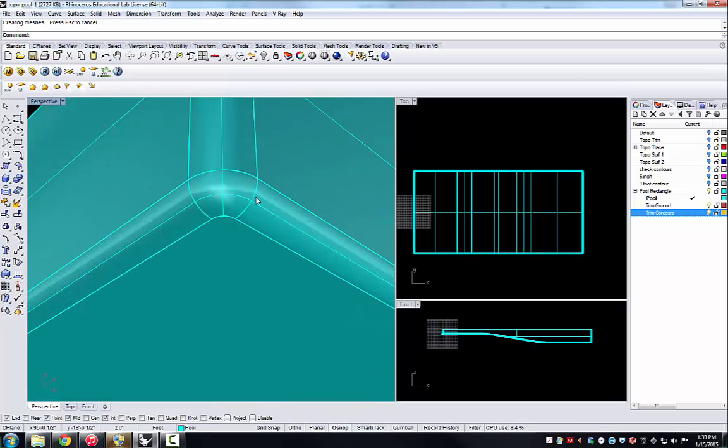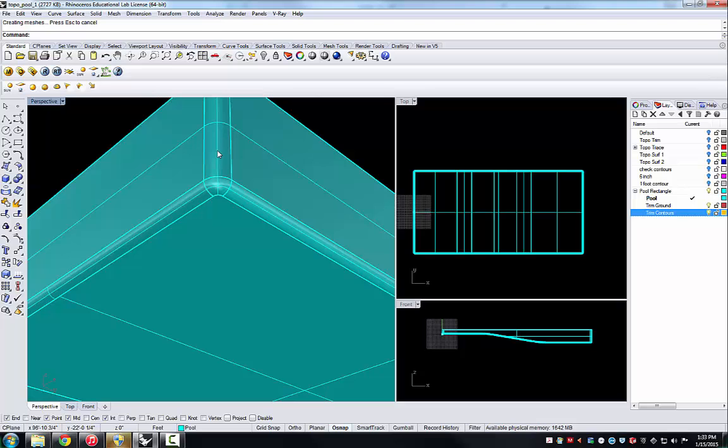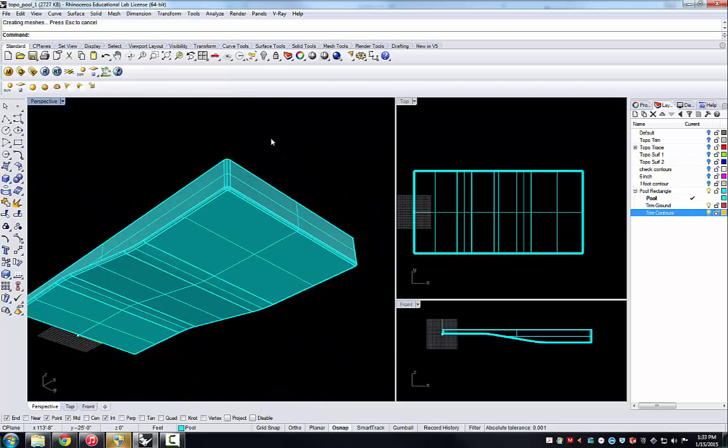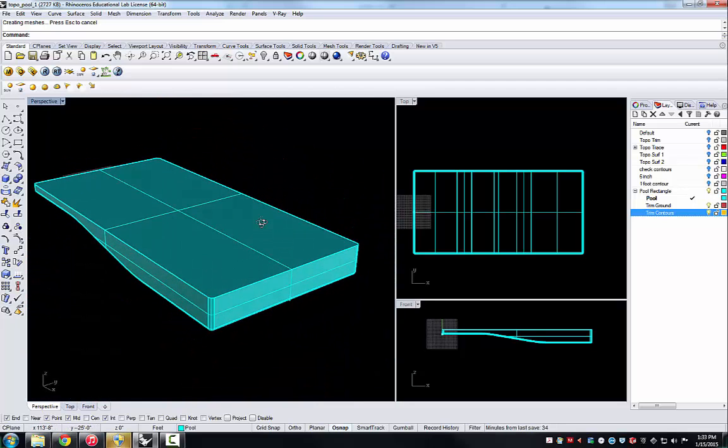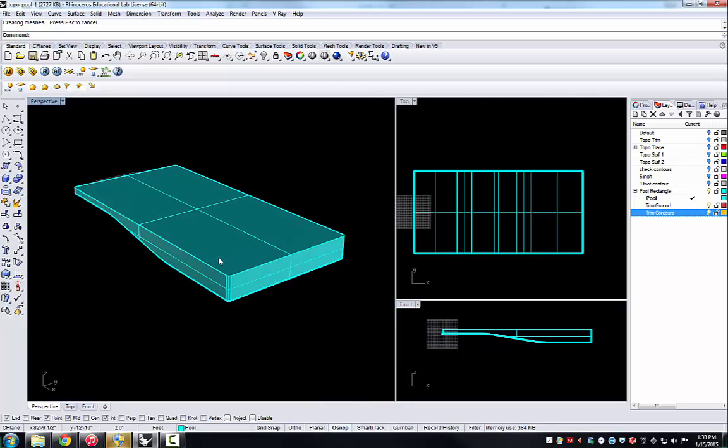If we had selected 12 inches for this bottom fillet, Rhino might have run into a bit of a logical problem when it came to a 0 point here. So it's helpful that the corner radius that we did first was 12 inches and the bottom radius is 8 inches. So now they work very nicely, and we have a nicely smoothed pool in its bottom and corner edges.